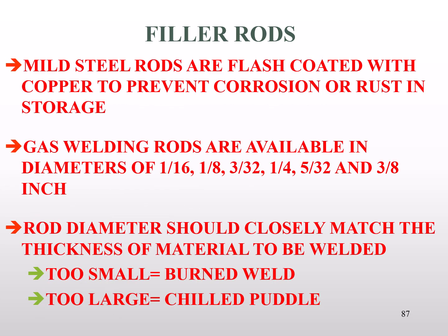Rods typically come in packs, sold by weight, and most of them, like I said, will be mild steel rods. But when you look at them, they have a shiny, bright copper looking finish. And that is simply because they are indeed coated with copper. Mild steel will rust. Well, rust is oxide.